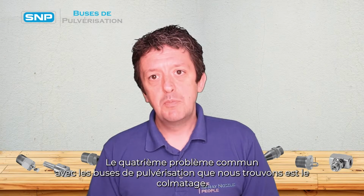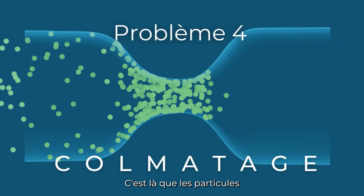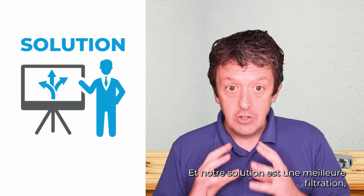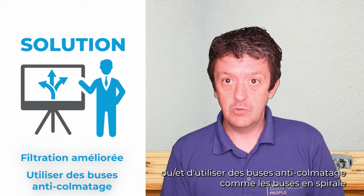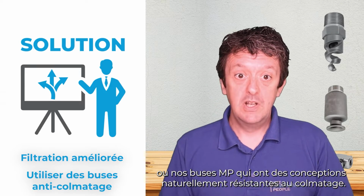The fourth common problem with spray nozzles we find is clogging. This is where particulates within the liquid build up within the nozzle and clog the orifice. This will obviously cause poor spraying. And the solution to this is either better filtration, so look at your filtration upline, and to use clog resistant nozzles like spiral nozzles or our MP nozzles that have naturally clog resistant designs.